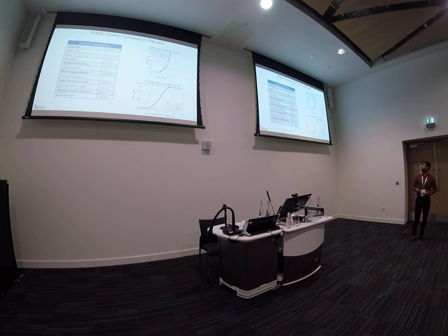And yeah, these are some sample simulation results using the model. This system's specifications are tuned for the Ampyx AP3 prototype, so the wing area of 12 square meters and some other parameters. One key thing to note here is the generator size. Even though the cycle average rated power is 150, you need almost 450 kilowatt to reach that rating at the desired wind speed. I'll show some details about it later.